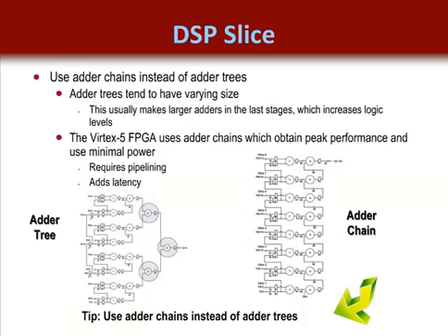When pipelined, the performance is approximately 500 MHz in the fastest speed grade, independent of the number of adders. To learn more about the process of converting a direct form filter to a transposed or systolic form, see User Guide 73, the Extreme DSP for Virtex-4 FPGAs User Guide. Likewise, you should check out User Guide 193, the Virtex-5 FPGA Extreme DSP Design Considerations document.